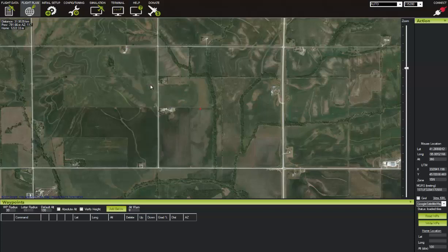Then tell the UAV what threshold altitude you want the automatic mode to engage in. In the case of using our bungee launcher, you would want to choose about 10 meters, while for a hand launch you would want to choose about a meter. From there, click OK and confirm that the 15 degrees of takeoff inclination is OK as well. We'll stick with that every time.